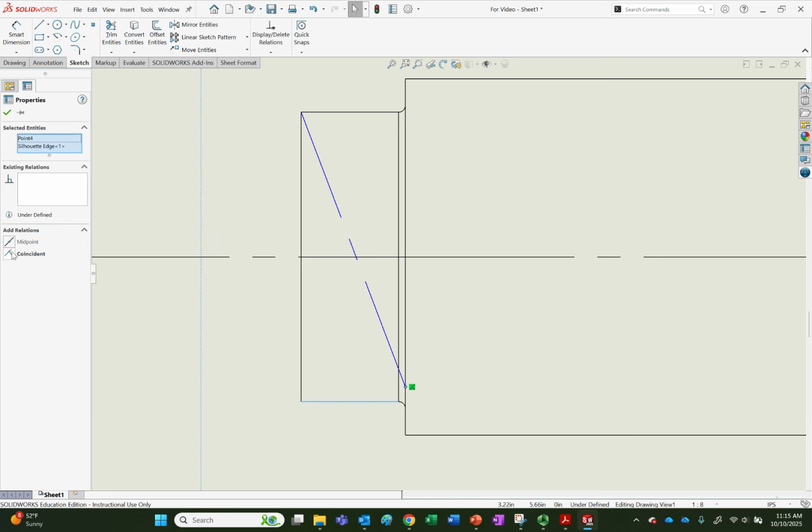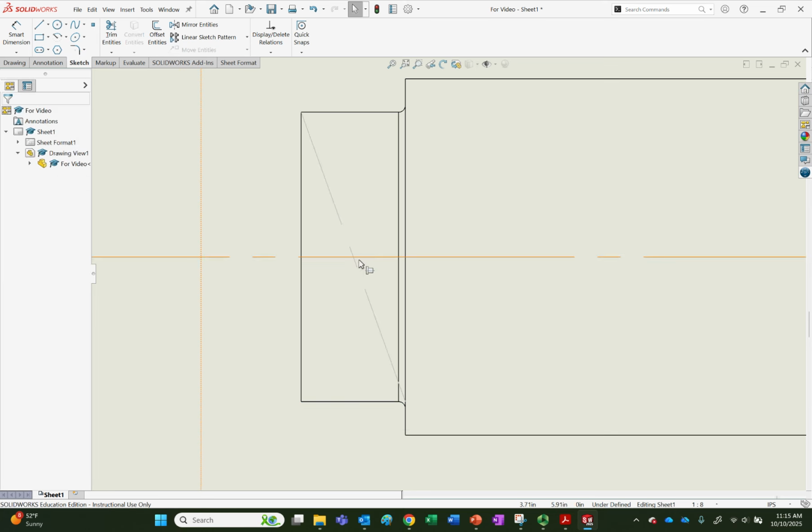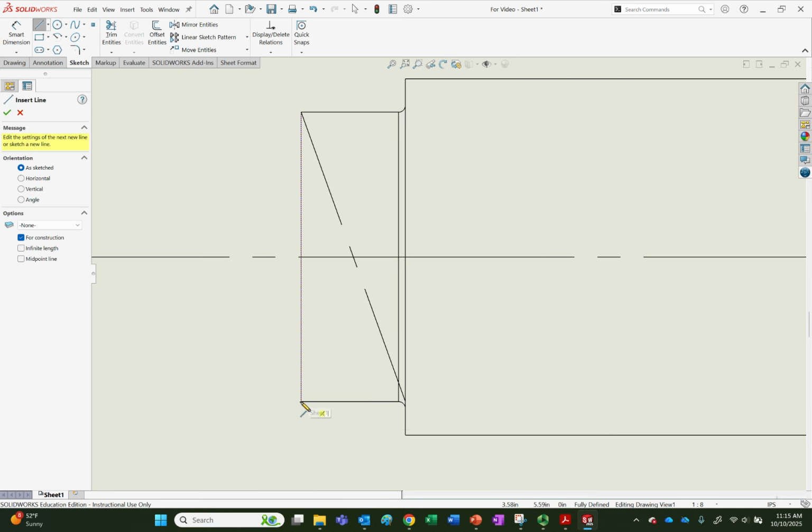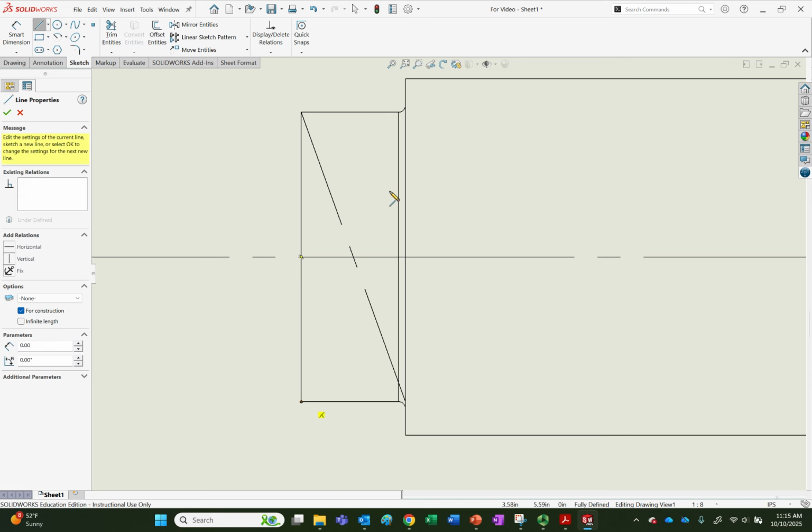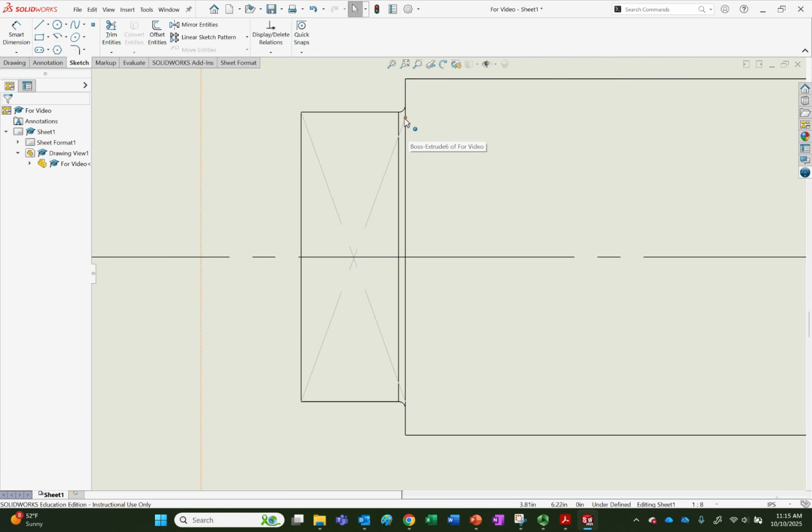And then I'm going to hit coincident. Now you can see that it makes it coincident to both that edge and to that edge. So that's going to establish the center of it. That's the reason why I'm doing it. And I'm using these center lines because they imply that this is not an actual edge on the piece, but in fact something that you're trying to give information about. So I did it again.